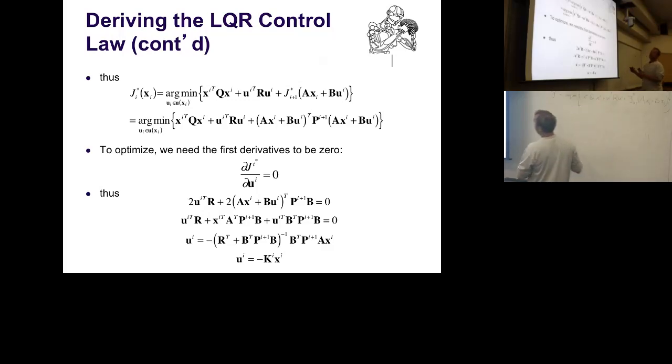Okay. And now we can basically say, we know that this has to be a quadratic function in state. So we start replacing this term simply by saying, okay, my state is going to be A x_i plus B u_i. Remember, this is nothing but x_i+1. I put in my P term. It has to be index i+1, and then I get this transposed, and I get A x_i plus B u_i again. So that was straightforward.